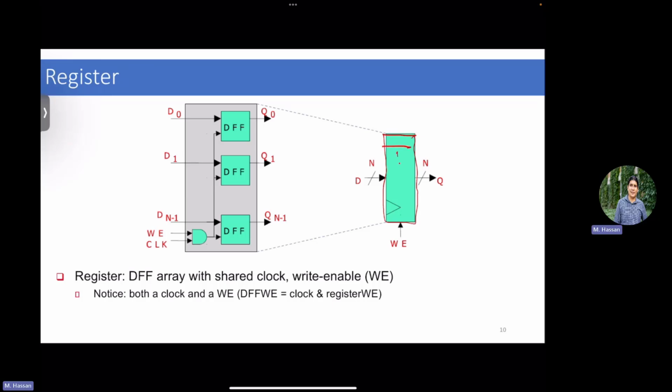that has some locations. In our MIPS ISA, we have 32 locations, and there is a data bus and there is an address bus. Well, there is an input port and an output port. In our case, if you remember, we said the register file implements 2 read ports and 1 write port, right, from our last lecture. And then we have the address to address one of these registers.